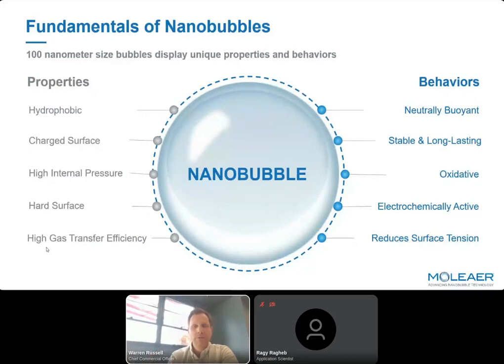Depending on the constituents in that water, it is possible to change that charge, but for the purposes of this conversation, we'll talk about this negative charge and its role in relaxing the hydrogen bonds in the water and consequently reducing surface tension. When you reduce the surface tension, we're also changing the contact angle, and the collective influence of those behaviors and how that affects the capillary action of the water is really what we're going to focus on today.